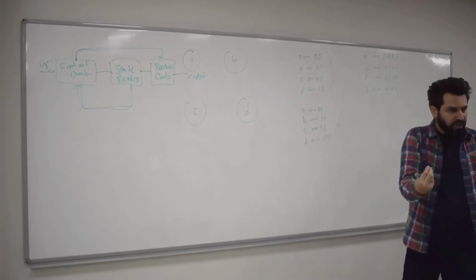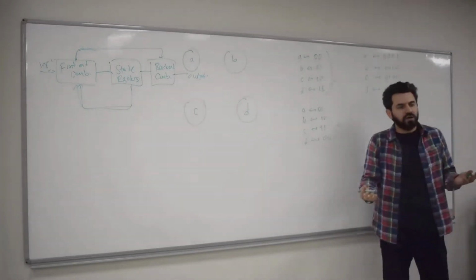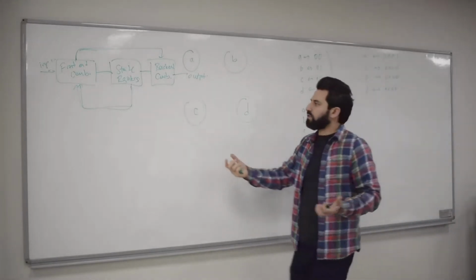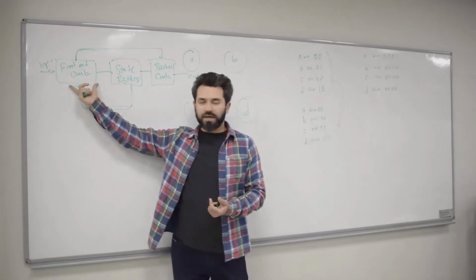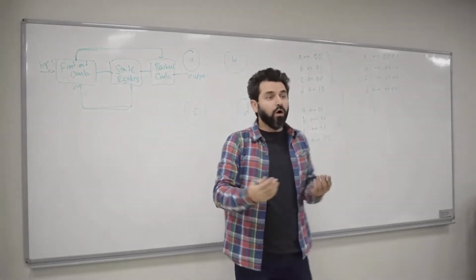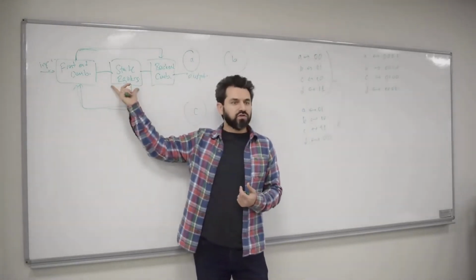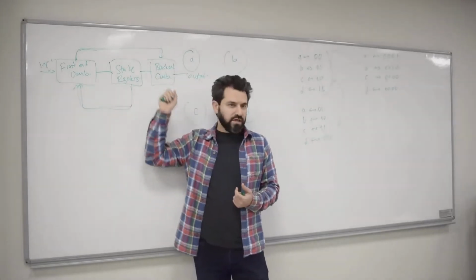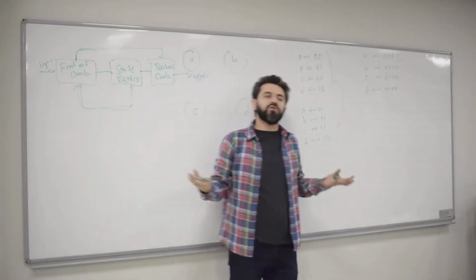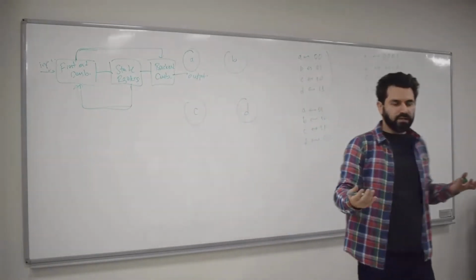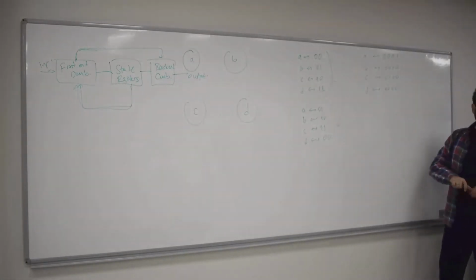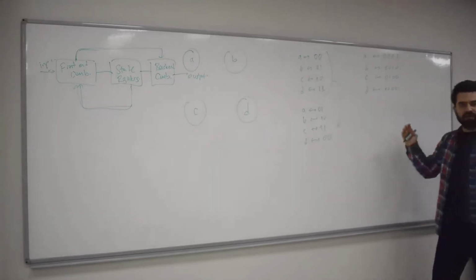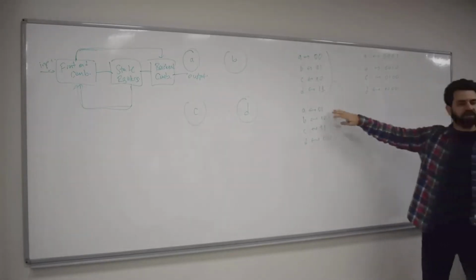Okay, given the same specification, you've got 2 design options. You can increase the complexity of the state registers by putting in more flip-flops and reduce the complexity of the front end and back end, or you can minimize the number of state registers and increase the complexity here. And which one is better? Well, it depends on the application. Depends on the application. Okay? And we'll actually have an example for these 2 particular assignments, by the way.